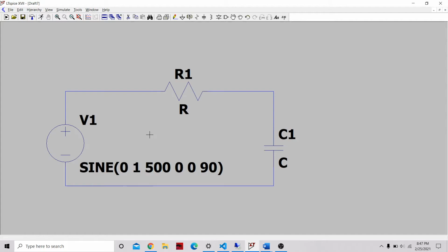All right. And a reminder, because this is effectively a node voltage solver, we'll always need to set a ground node. So let's set a ground node here at this common terminal. It has the most connections between the different components, so it will serve as a good ground and reference source.